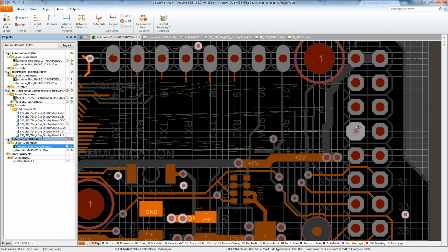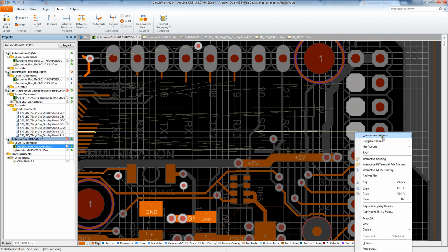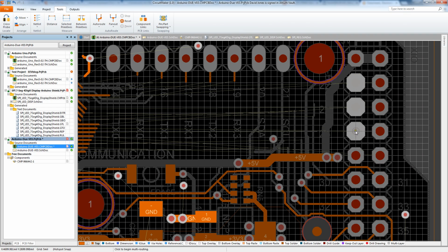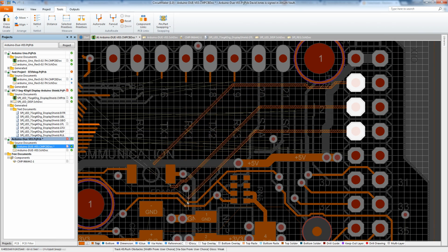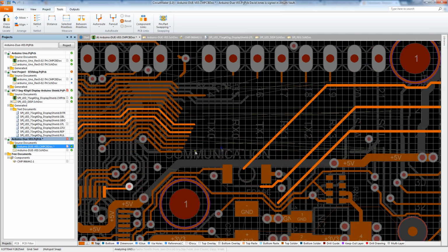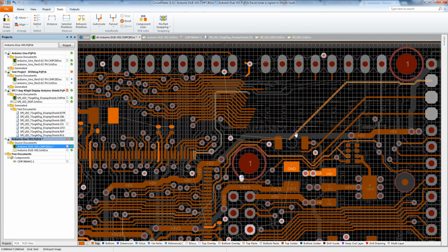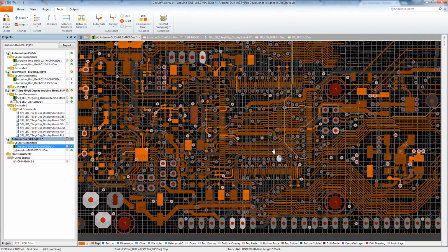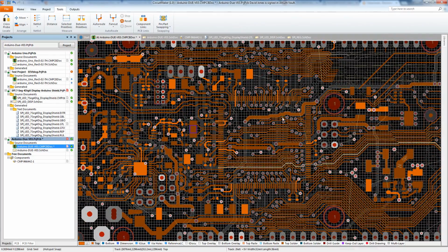So, of course, it's got all that lovely interactive multi-routing and things like that. This won't be the world's best example, but I can go in here and go interactive multi-routing on these 3 pads. I haven't set up all my routing rules and things like that, but you can set for push and shove. You can see the traces down there just push and shove around. So it's got all the usual powerful routing capabilities of Altium Designer. I love it. It's fantastic, and it's free.